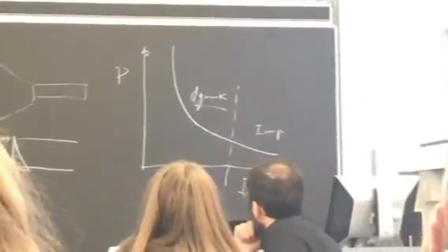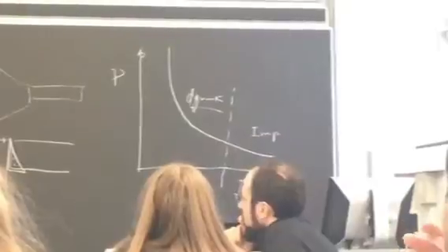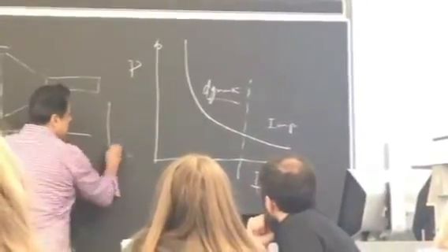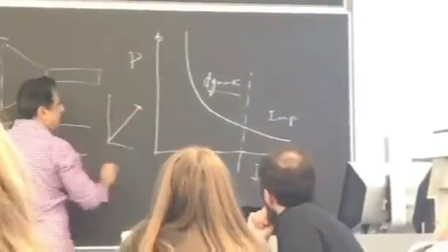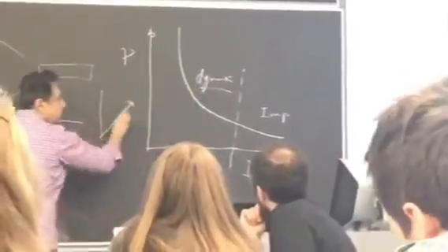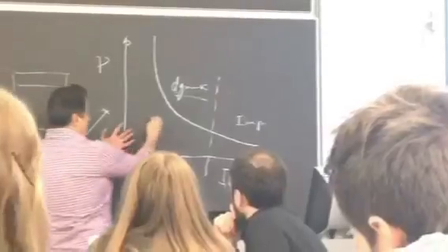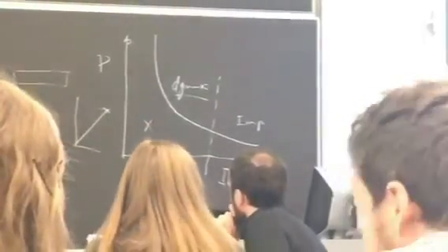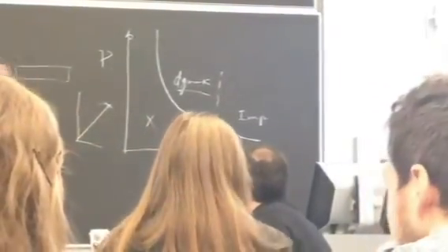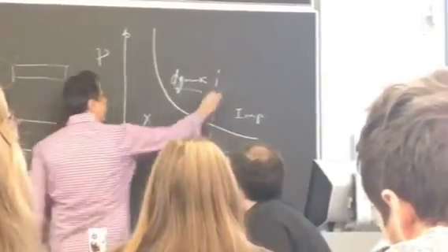So essentially, I can say in a system that looks like this, that fails at this point, this is the iso curve that represents that exact point. If I'm less than this iso curve in terms of pressure impulse, I'm good to go. If I'm larger than that, then the system has failed.